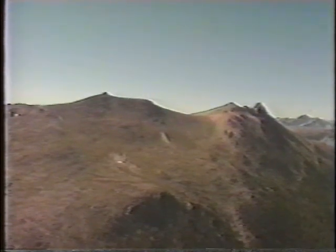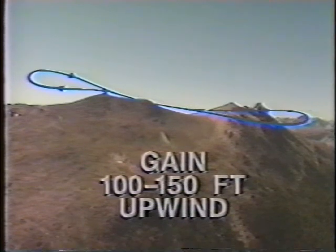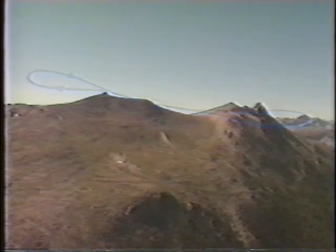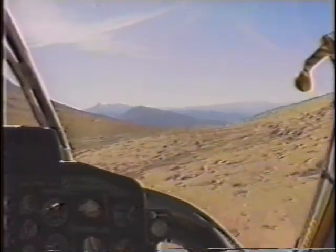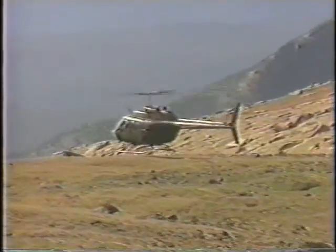Small, deep-set saddles require a modified figure 8 recce. Gain 100 to 150 feet on the upwind side before you pass over the saddle to compensate for the lack of drop-off downwind. Stay in the boundary layer and work down to low overshoots, only going upwind.